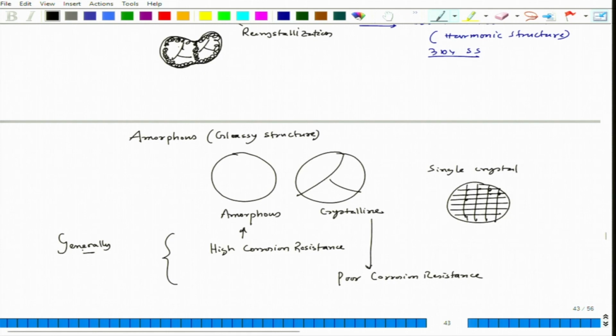Generally, okay. Now, whenever we talk about amorphous, mostly they are multi-component. Okay. In a single element, making amorphous needs a very high cooling rate. So the cooling rate requirement usually does not allow it to be amorphous, it will always crystallize. But there are multi-component systems where amorphous phase formation becomes very easy. There are several reasons for that. It is itself a field of study, how amorphous phase forms in a particular material, whether metallic or non-metallic, it does not matter.